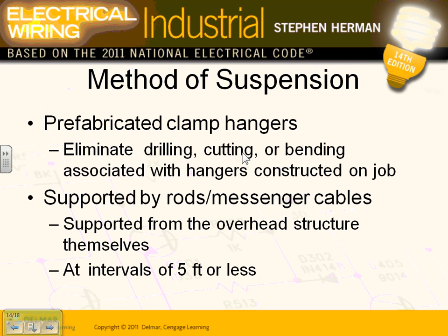Suspension. You have to suspend this system, guys. You have some type of hangers, you look at them, and they have to be supported every 5 feet by code, unless the manufacturer tells you otherwise. If they're listed and labeled to be supported every 10 feet, then you support them every 10 feet. Otherwise, the rule is every 5 feet.